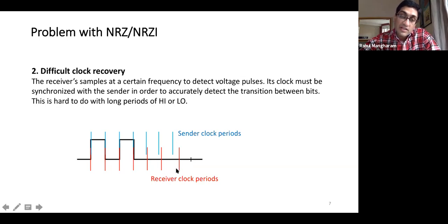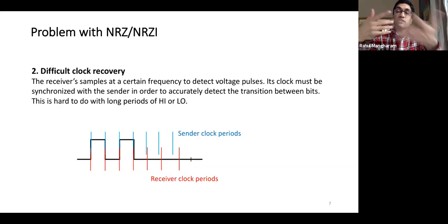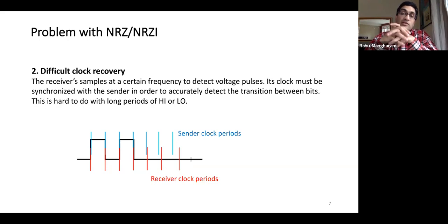The receiver's bit count over here, the time for a bit is larger than the sender's, and it's also offset, right? But it's also not offset the same amount. Sometimes it is offset a little, sometimes it's offset more. So from bit to bit, I'm just offset from you slightly, every time. That is called jitter over here, right? That means you are jittering and I'm jittering.